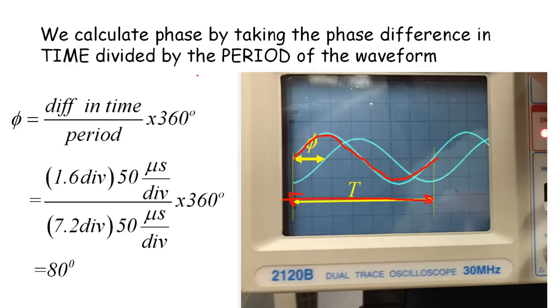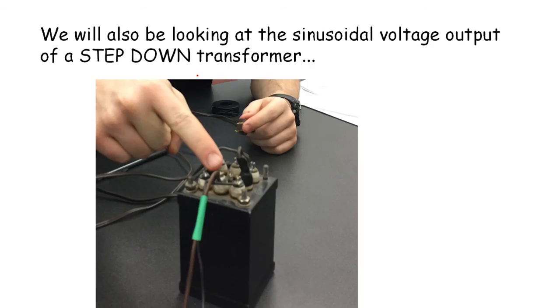This is the period, and that looks like 1, 2, 3, 4, 5, 6, 7.2 divisions times 50 microseconds per division. So that's another time. You're dividing the phase in time by the period in time, and that's the fraction of a wavelength that is the phase difference. You multiply by 360 degrees to get the phase angle. You probably know that from your trig course. Okay, and that's the end of that.